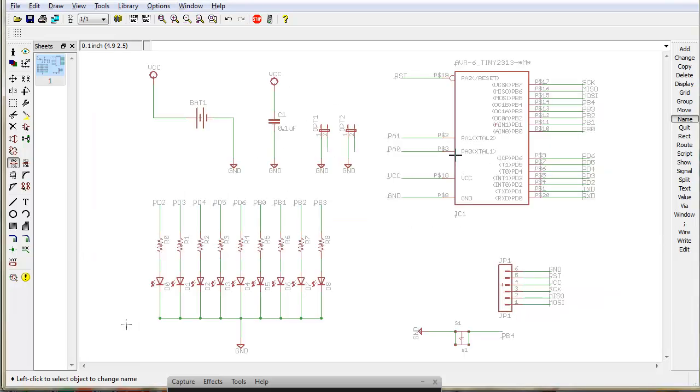Now, obviously, since we're not doing an electronics class here, it could be difficult for some people to follow, but basically all we've done is connect from ground through the LED through a resistor to PD2 on the CPU to over here, and then these are basically jumpers, just like the normal type you're probably used to seeing. It's basically just going to be two holes on the PCB connected to ground, which then is going to run from here all the way over to PA0 and PA1, which are these two here.